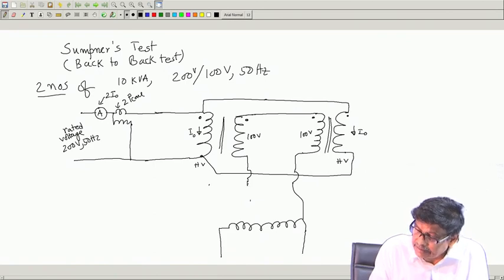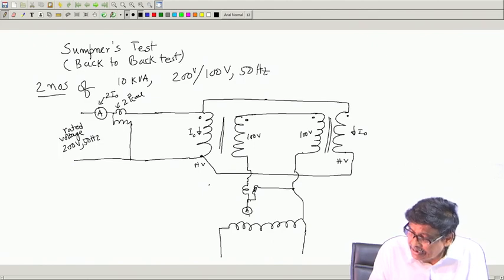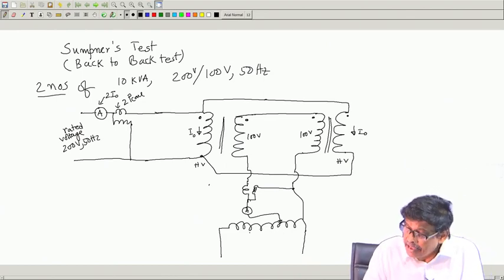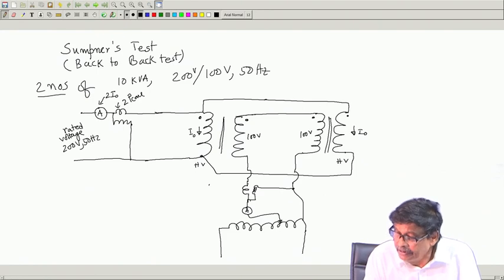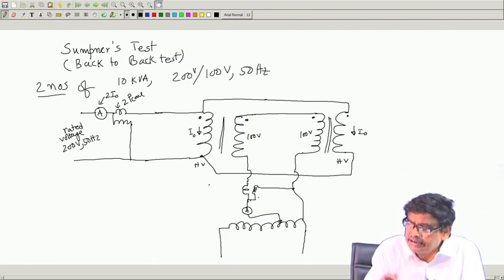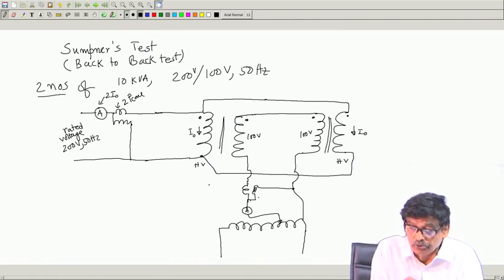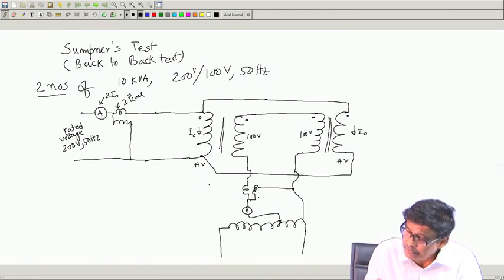And here once again you connect a wattmeter and an ammeter, and make an arrangement so that you can apply a small voltage across this. If the pointer was at this point, no voltage applied, and the net EMF acting in this circuit is 0, nothing happens. Now, what you do with the primary energized, mind you,